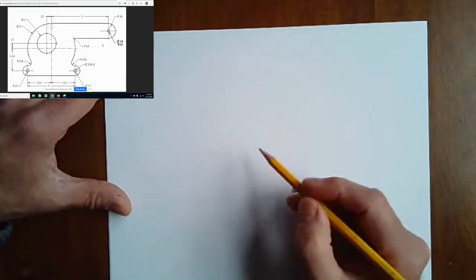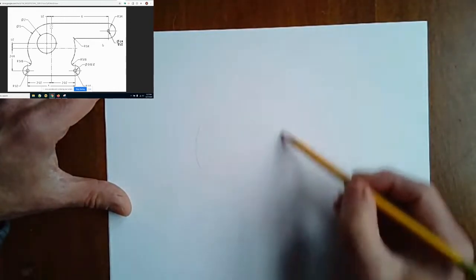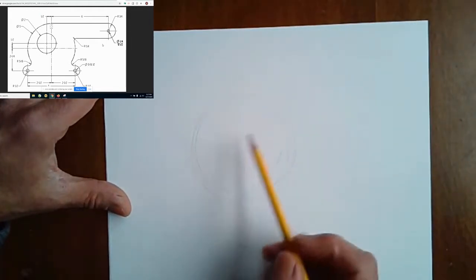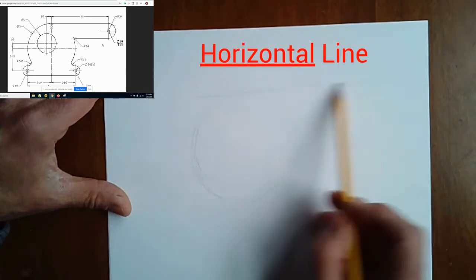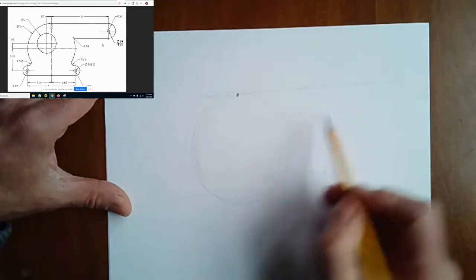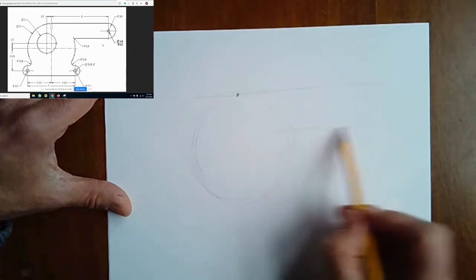So on paper, what this looks like, and again, you may notice that I'm going to start with light construction lines, and I'm going to sketch something that roughly looks like a large circle. The top edge is simply a line that is tangent at this one point. I may draw the thickness of the helicopter tail right here.